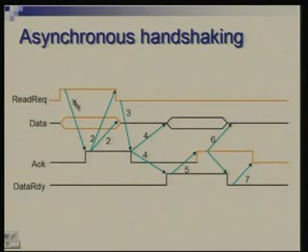There is a sequencing shown by arrow 1, another sequencing shown by arrow 2. These events have to occur in this particular order. Another response to this change is that since data has been read, it need not be kept on the bus. So it can be removed from the bus and the bus becomes free.